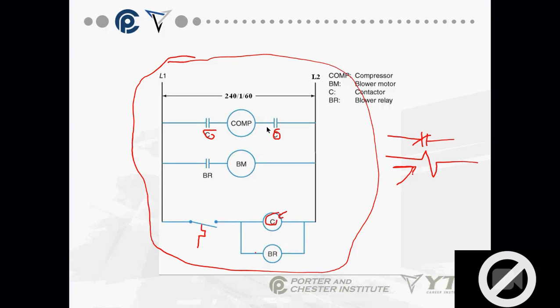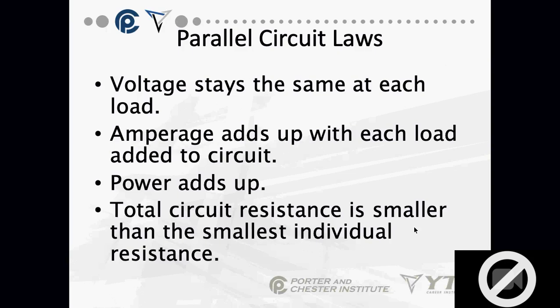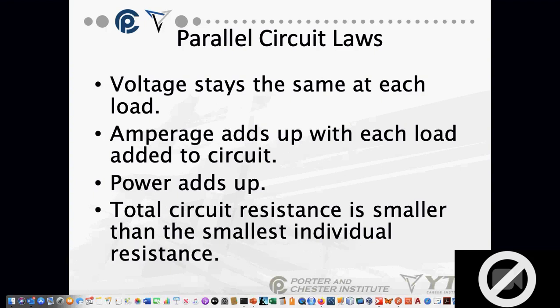Again, we're going to spend some more time on relays and contactors, but just remember that these both are getting full source voltage, so their resistance really doesn't matter. So in a parallel circuit, voltage stays the same at each load, and amperage adds up.